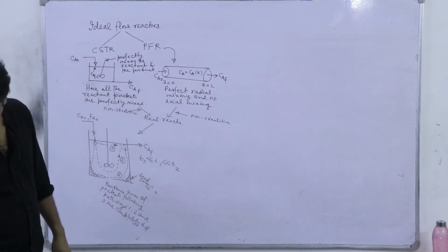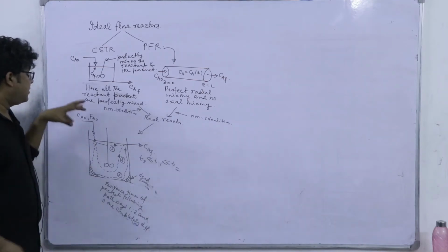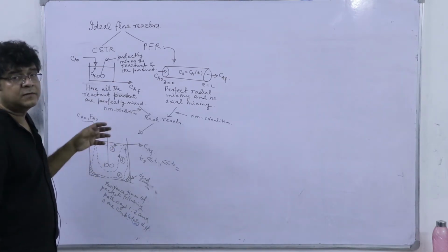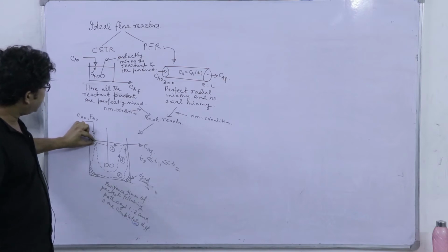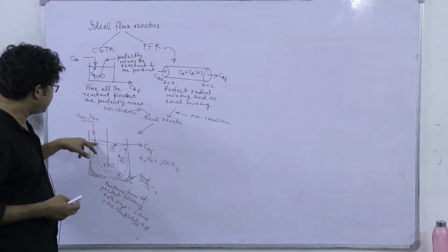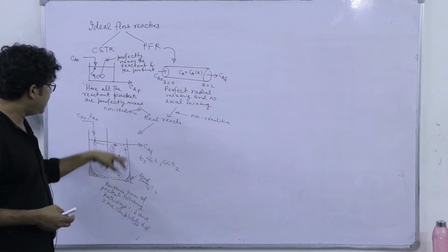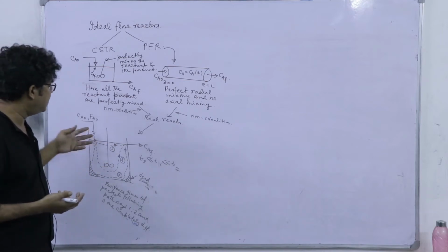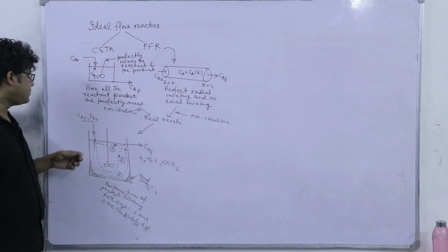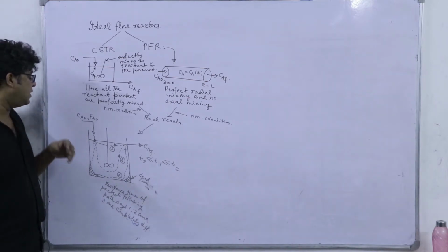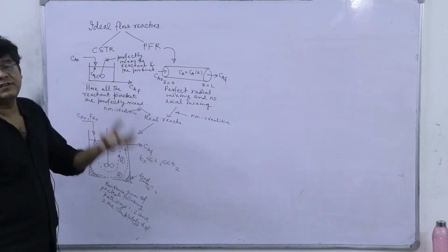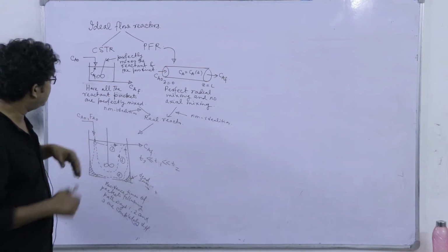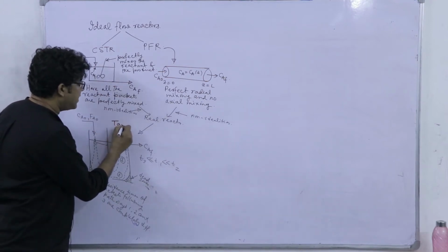So the point we have to note is that all the reactant packets do not have the same residence time and they are not perfectly well mixed, because there is practically no interaction or mixing between the packets following pathway 3 and those following pathway 2. So obviously there will be a difference of residence time, which triggers different extents of mixing, and this gives rise to what we refer to as a non-ideal tank reactor.